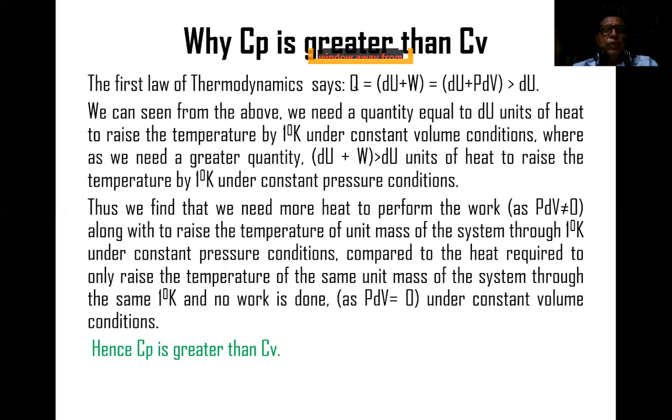Thus, we need more heat to perform the work, as PdV is not equal to 0, along with raising the temperature of unit mass of the system through 1 Kelvin under the constant pressure condition, compared to the heat required to only raise the temperature of the same unit mass through the same 1 Kelvin when no work is done, as PdV is equal to 0, under the constant volume condition. Hence, Cp is greater than Cv.